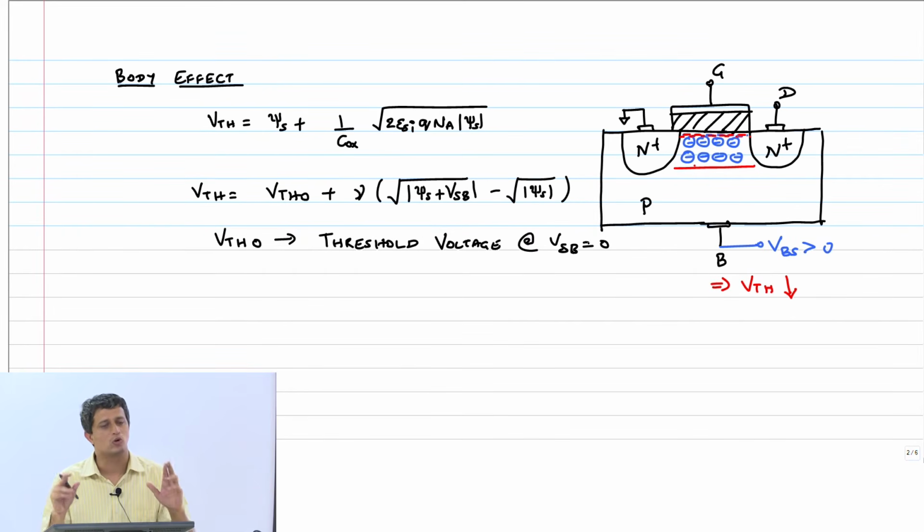So what we are doing is known as a compact model, which means that whenever it becomes very complicated or difficult to model something, you resort to an empirical model. So that parameter you will just fit, which means that if I take the previous equation and scale oxide thickness Tox, I can guarantee that the threshold voltage will vary as per this equation. Now here when I do this empirical fitting, if I change some parameter, there is no guarantee that it will work.